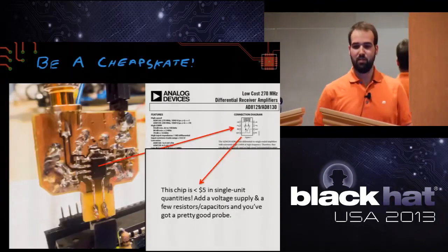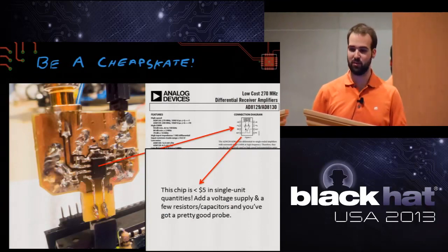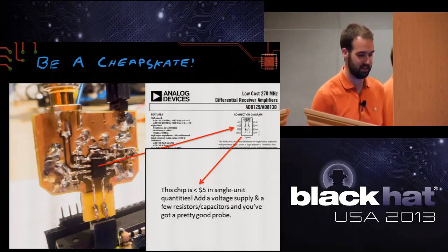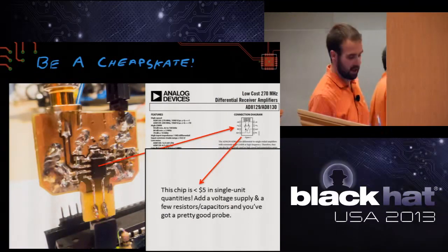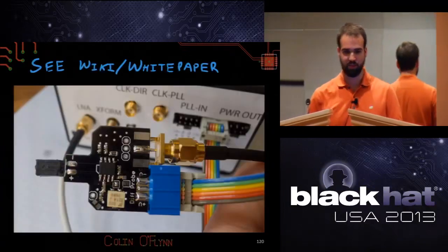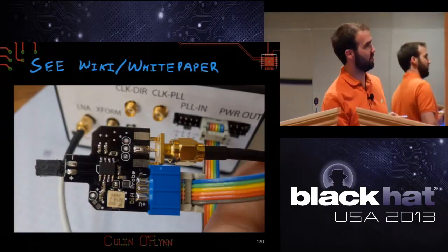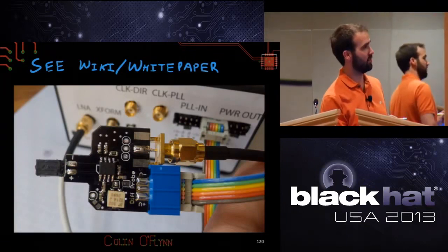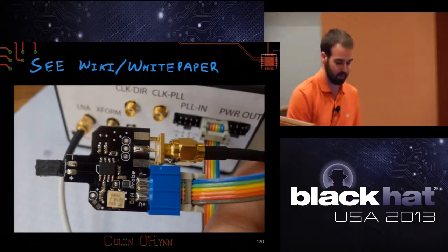But you can build something for what we're doing that works well enough, has pretty good high frequency response for about $5 using this, or with a $5 chip, plus a few other parts. And this chip will work more than well enough. And there's a nicer version now with PCBs and whatnot. So this shows you the design of the ChipWhisperer in the background. There's this differential probe, and you just plug that onto the board.